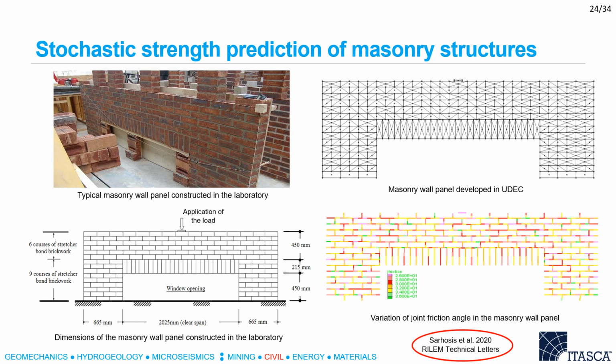In the present work, a probability distribution of the material parameters for the masonry constitutive model has been considered. The mean values and the coefficient of variance for the masonry units and mortar were used to define the material parameters in the model. In particular, the realization of the material parameters was randomly assigned to every brick and mortar joint as shown in figure on the bottom right-hand side corner. To achieve confidence with statistical results, 300 simulations were created. The computational time for the 300 simulations was 48 hours.